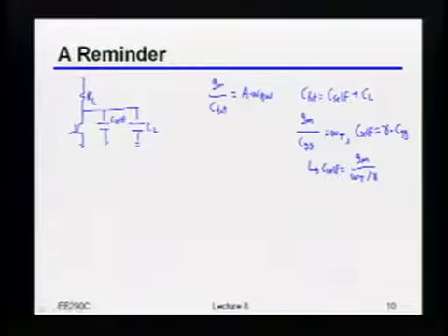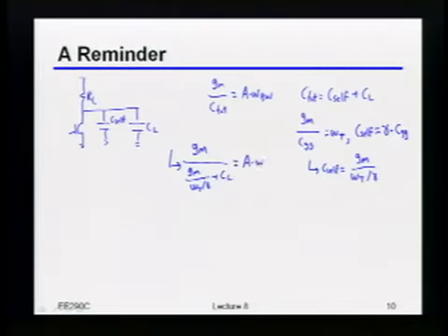Okay, so this is now nice, because I can write one expression that is just in terms of the GM. In other words, GM divided by the total cap, which is GM over omega t divided by gamma, plus the real explicit capacitance, is equal to A times the bandwidth that you need.